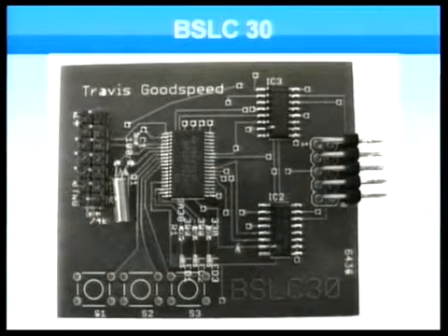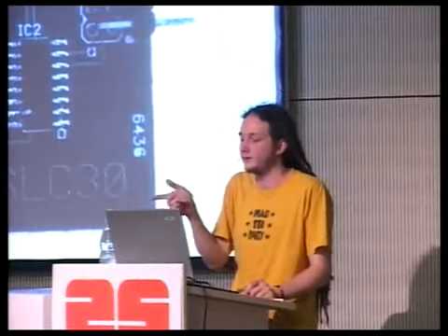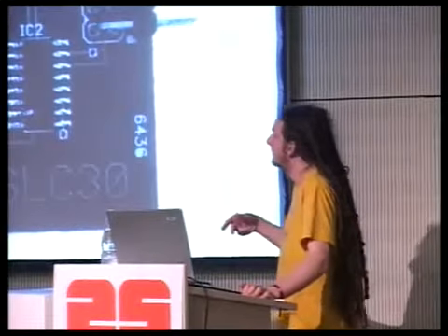These two chips on the right are both 4053 muxes, which can be used to do a voltage glitching attack on the device that you're communicating with. And at this point, all of the I/O lines are switched to high impedance so that no power can be sucked out of them. And then the voltage line drops to a lower voltage that's controlled by an I/O pin. By use of this, you can glitch past a disabled BSL. With better firmware, you should be able to glitch past the password comparison itself. If you glitch through it such that it never actually compares a byte, then it can never disable your access.